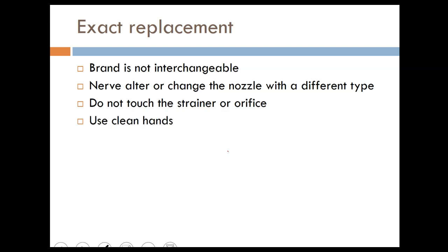Use clean hands. You might be working with oil with some grease. If you put any kind of stains on the nozzle, it's not going to function. If you look at it, it's very, very fine details in the mesh. A small grain of sand or dust that goes into the spray angle will change the way it sprays. And if it sprays incorrectly, it will cause you to drop some oil in the chamber. And that's a problem because you'll have a lot of smoke.